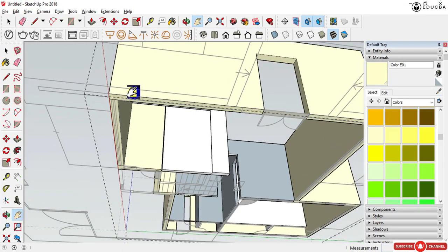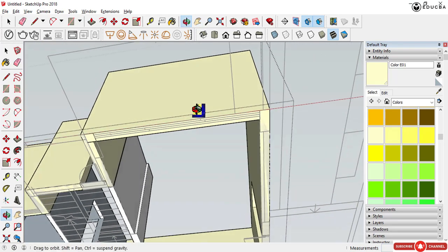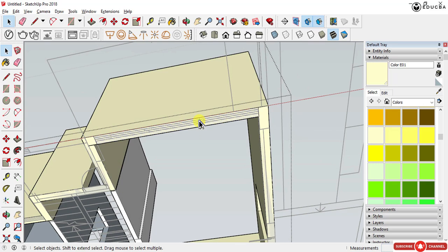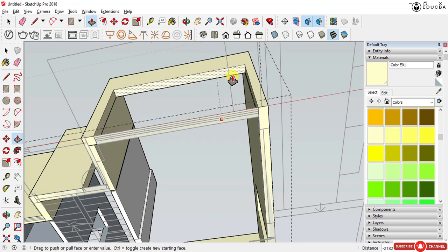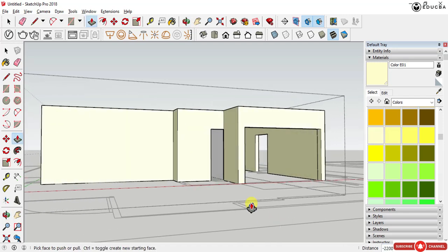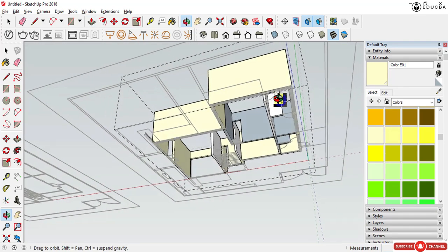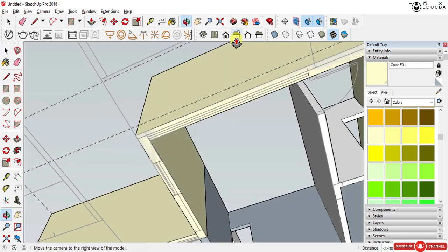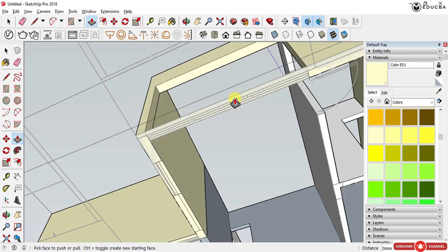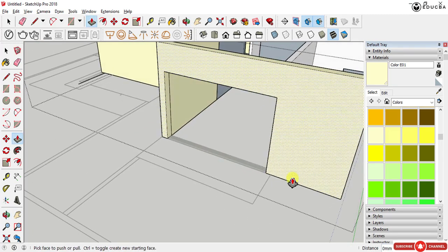Now as you can see at the bottom, you have these windows to be made, some of which are French windows, for which I'm going to identify and then push them to 2200 sill level. There is one window. Here we go for another. And you can see after double clicking, the push command pushes it back to 2200 level.